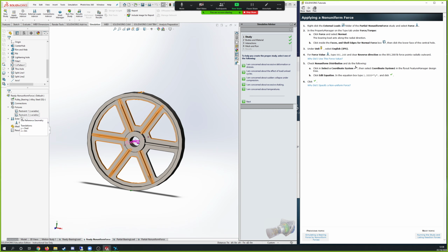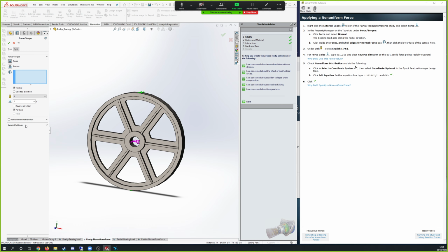So you can understand how it is actually deforming, it multiplies it by a certain amount. Oh, it's exaggerated, because when you make it true scale, you can't even tell that it's deformed. Yeah. So if you want to look at the way that it's actually failing, it's easier if there's a bit of deformation. Usually you change the scale to something that's not like 2000, so you can actually see the response.